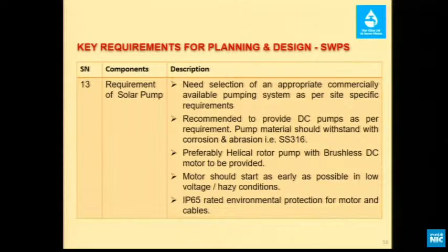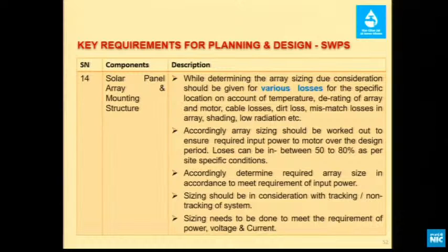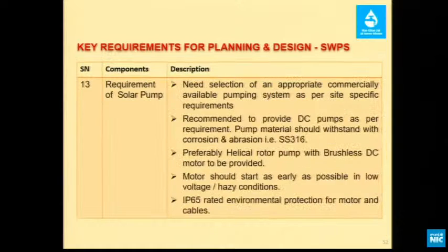So this is required. External World Bank studies suggest that in Bihar and UP, most of the pumps used to get choked, or abrasion has taken place in the impeller of the pumps. So naturally, I need to ensure that the pump material should be of appropriate quality. I suggest that it may be of SS grade 316. This is my suggestion, which I will study.